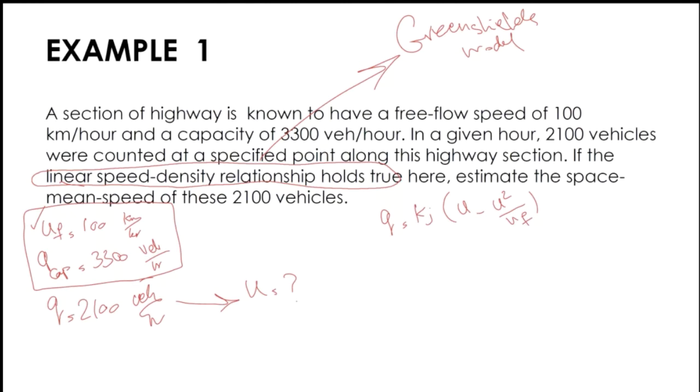So let's plot some of the fundamental diagrams here schematically first. Let me erase this for now, so I have enough space to draw the fundamental diagrams. So if I plot the fundamental diagram relating density and flow, again, we're going to go with Greenshields model, so it's a parabolic shape, right? And I know the Q cap, so this is Q cap, which is 3,300.